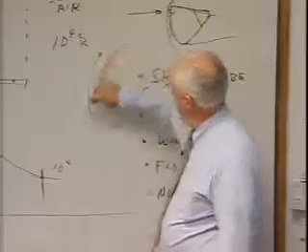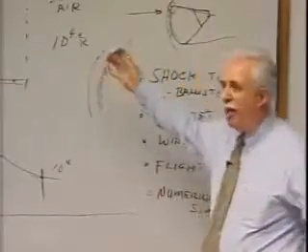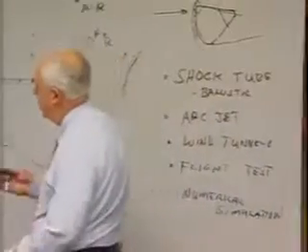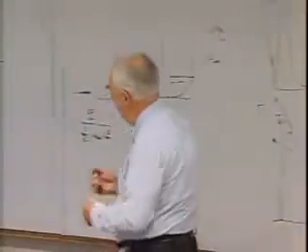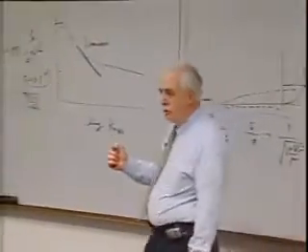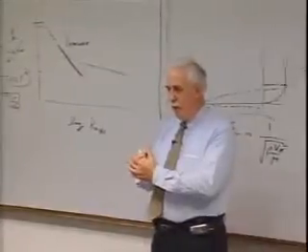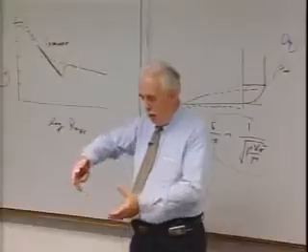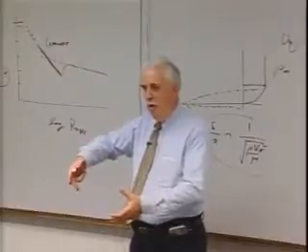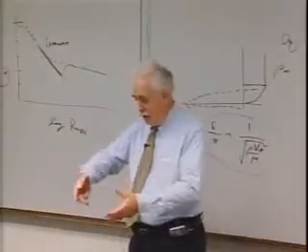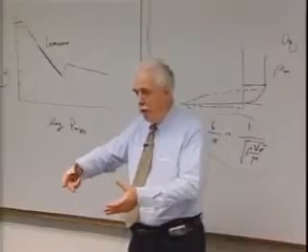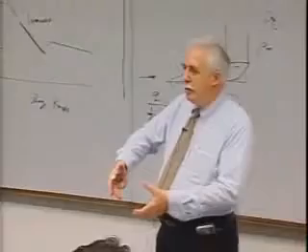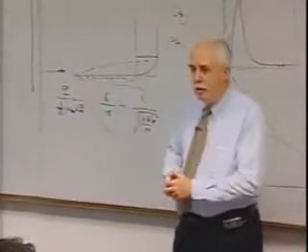So the combination of the two-dimensional flow, which we really hadn't simulated on the ground, all we could do in the arc jet is basically little pucks to test the ablator, okay? You're dealing with an awful lot of energy, and if you spread that energy over a large surface, the enthalpy basically goes down, the heating on the surface goes down. So we were testing 6-inch type specimens characteristically.